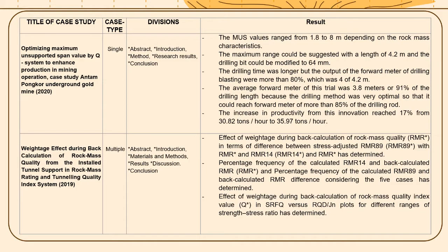For the result, the maximum span could be suggested with a length of 4.2 meters and the drilling bit could be modified to 84 millimeters. The drilling time was longer, but the output of the forward meter of drilling and blasting was more than 80%.